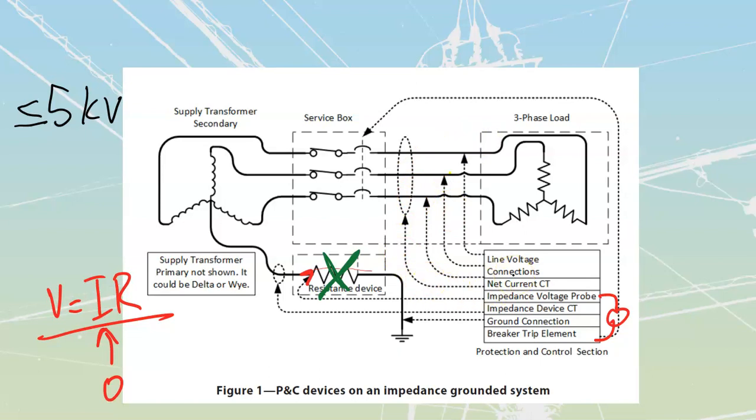However, as soon as we would go into a ground fault, if this line would fault out, we would see that some of that current would return, just erase that one there, would return through here, which means that it is now outside of this window, which would mean that now our CT is going to register a small amount of current inside there, which is going to give us a trip signal as well.